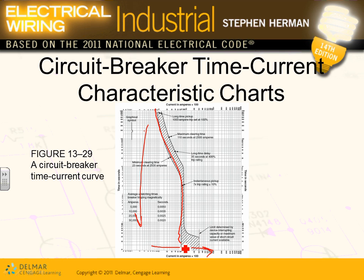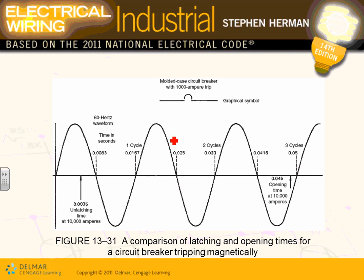You can see the curve here. This is your overload condition here. This is your short circuit condition, and in between is the melting or the opening region for this time current characteristic curve. We'll look at this one in a second in a better view.